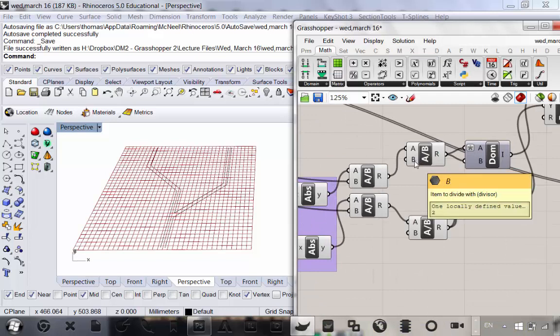And then what we need to do here is, I'll draw this out. The domain in Grasshopper: if the width of the rectangle is 2, and let's say in this direction it's 4, we have a rectangle that looks like this. To center it on the point we want, since the rectangle is based off its center point, we need to divide this by 2.